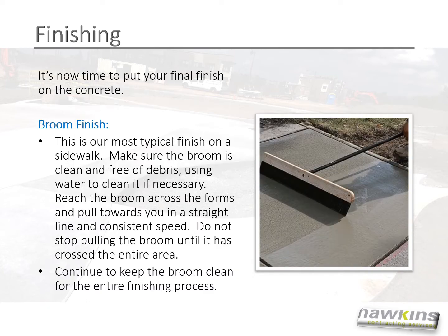It's now time to put your final finish on the concrete. Broom finish. This is our most typical finish on a sidewalk. Make sure the broom is clean and free of debris, using water to clean it if necessary. Reach the broom across the forms and pull towards you in a straight line at a consistent speed. Do not stop pulling the broom until it has crossed the entire area. Continue to keep the broom clean for the entire finishing process.